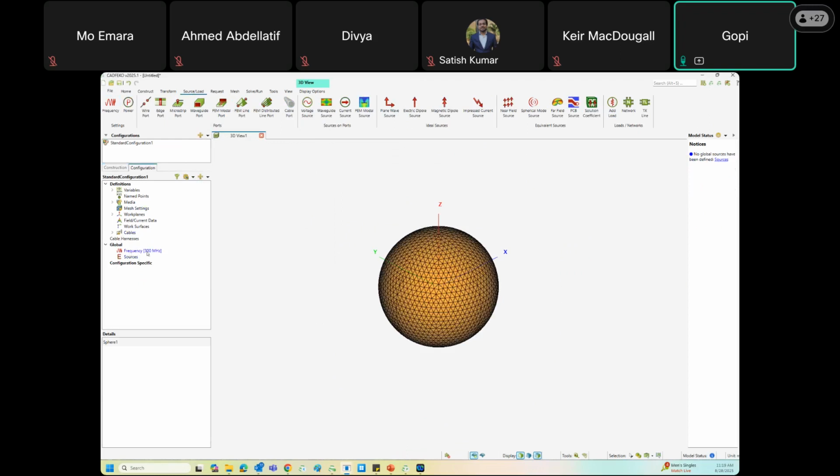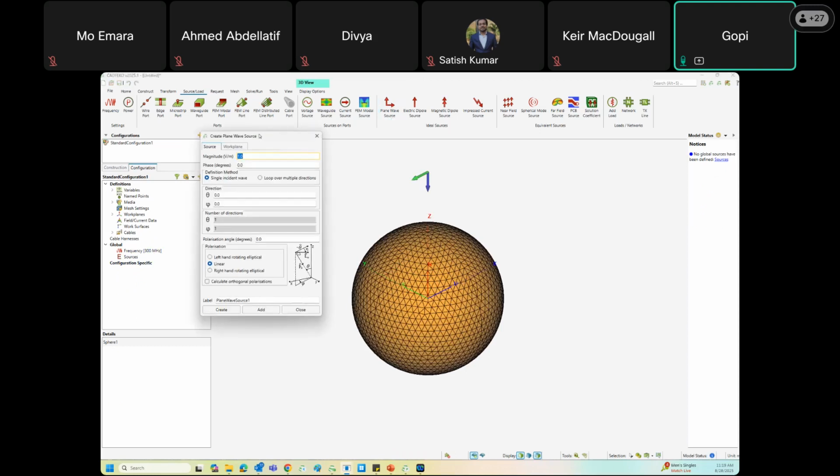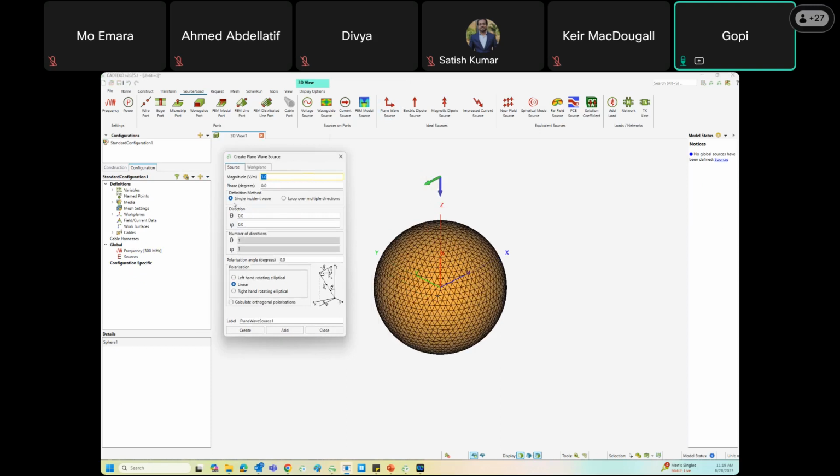So you can see as soon as I specify frequency, depending on the frequency as well as the material properties of the geometry, Feko will automatically mesh the model. And then for computing RCS, we use a plane wave as an excitation. So you can click on plane wave. And this is where you have an option to specify the incident direction, whether it is a single incident wave or you want to loop over multiple directions.